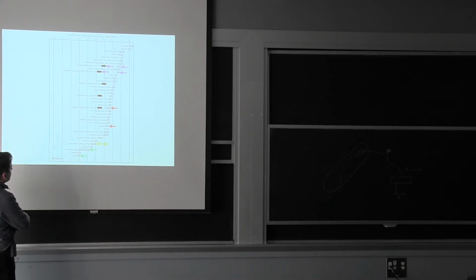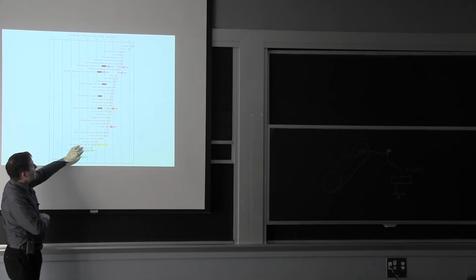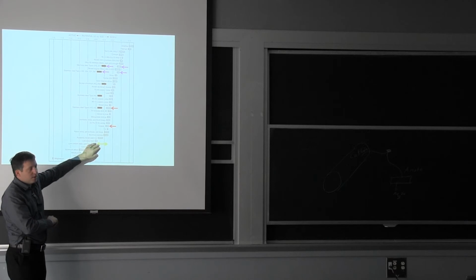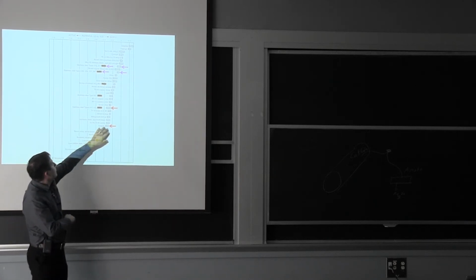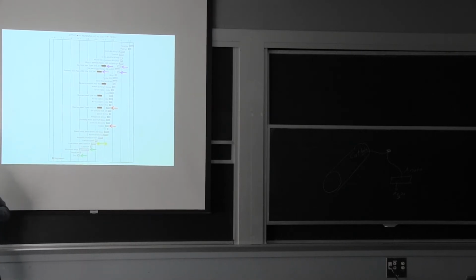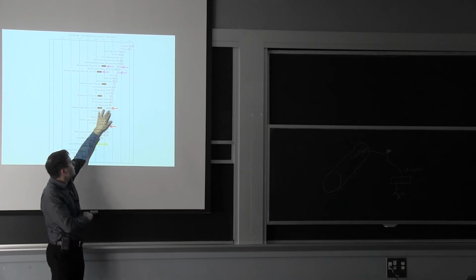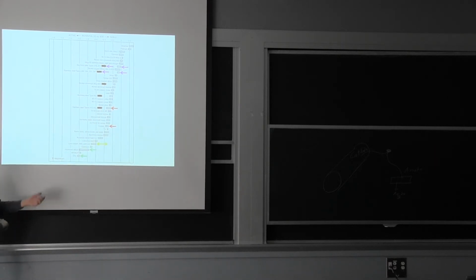The practical aspect of it, the reason I've put some arrows, is you can see a little bit aluminum is very reactive with all the other material. When you talk about regular iron, it's kind of in the middle of the road, and then you have the copper and the stainless steel that are more resistant if they are in the passive state. So stainless steel here, if on the surface somehow you lost the passivity, then it becomes very close to a regular carbon steel, and that will happen sometimes underground, and you don't know exactly why.